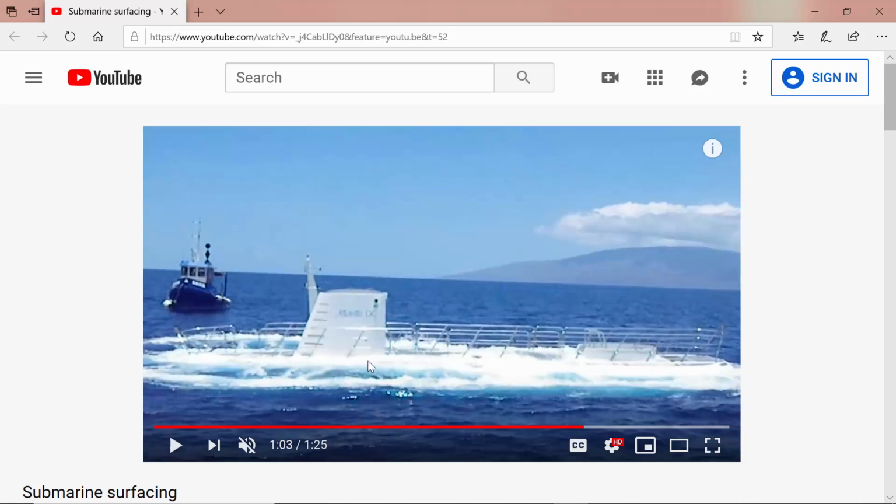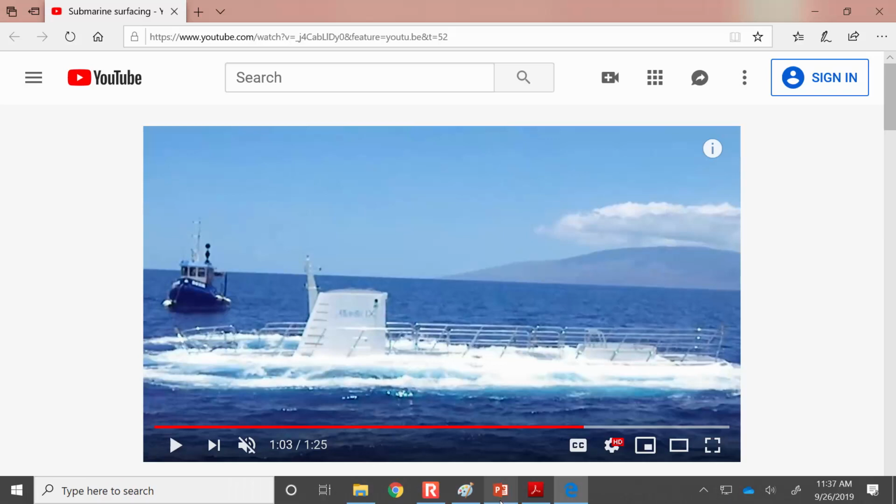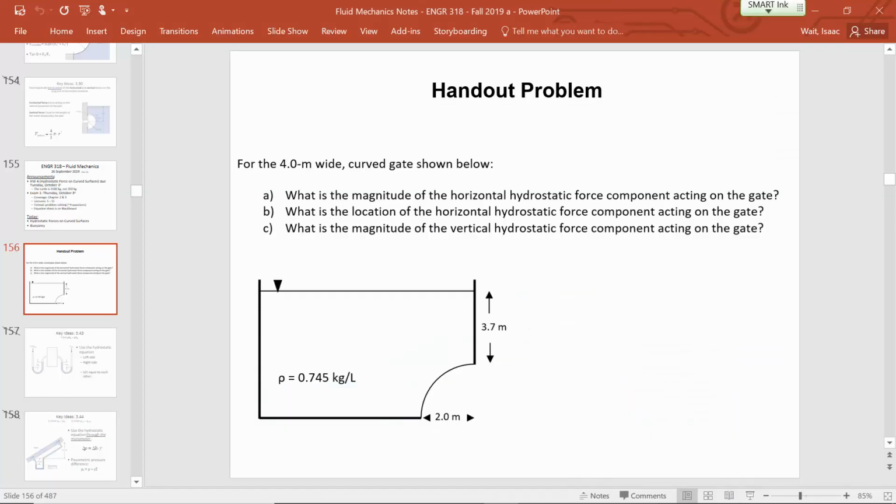That's the key idea to understanding the buoyancy that the submarine is experiencing: the magnitude of the buoyant force is equal to the weight of the water that the submarine pushed out of the way. So when the submarine starts sucking water in, some of that water that initially it had pushed out of the way now gets to take up the same volume that previously was being displaced. And that's what increases the weight and makes it greater than the buoyant force. So we're going to get into all of those details today.